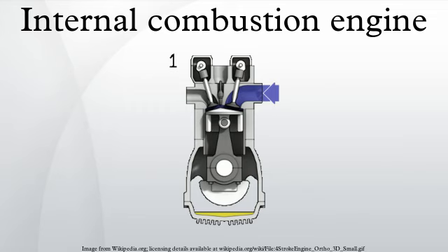Otto cycle. The Otto cycle is the typical cycle for most of the car's internal combustion engines that work using gasoline as a fuel. The Otto cycle is exactly the same one that was described for the four-stroke engine. It consists of the same four major steps: intake, compression, ignition and exhaust. PV diagram for the Otto cycle.